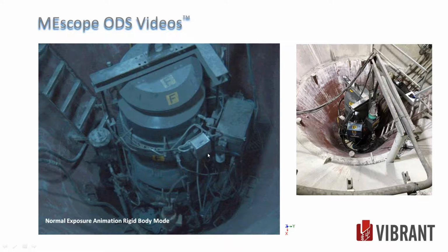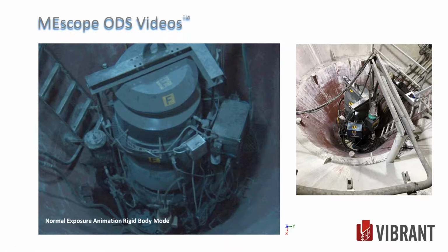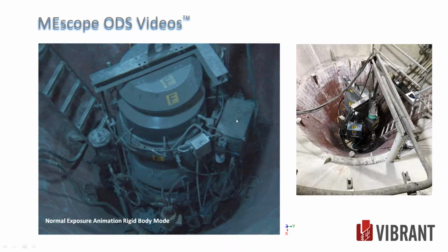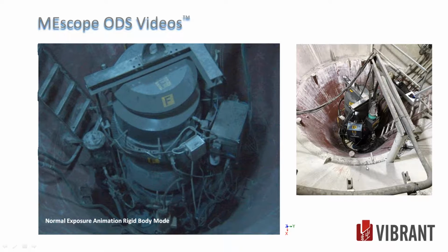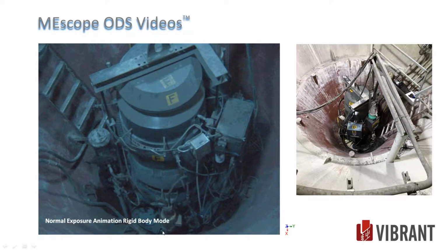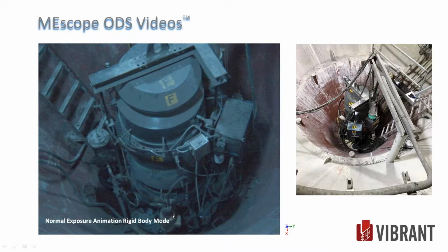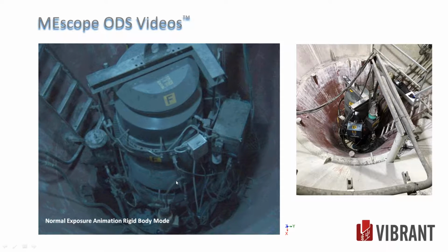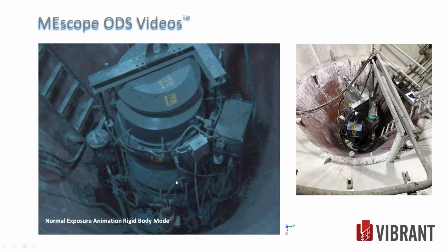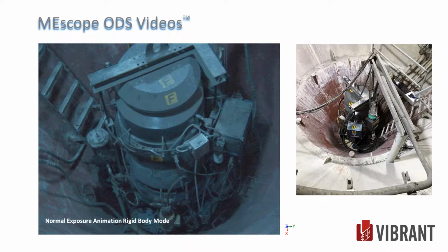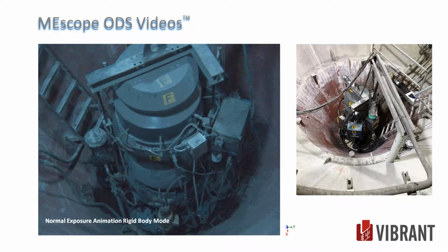Originally I thought that can't be right. It looks too rigid body to be something like this, and I assumed it was bolted down tight down here to something, to a foundation, but it's not. It's suspended. So this makes perfect sense. So this is a lower frequency. I think it's 1700, something like that, CPM.